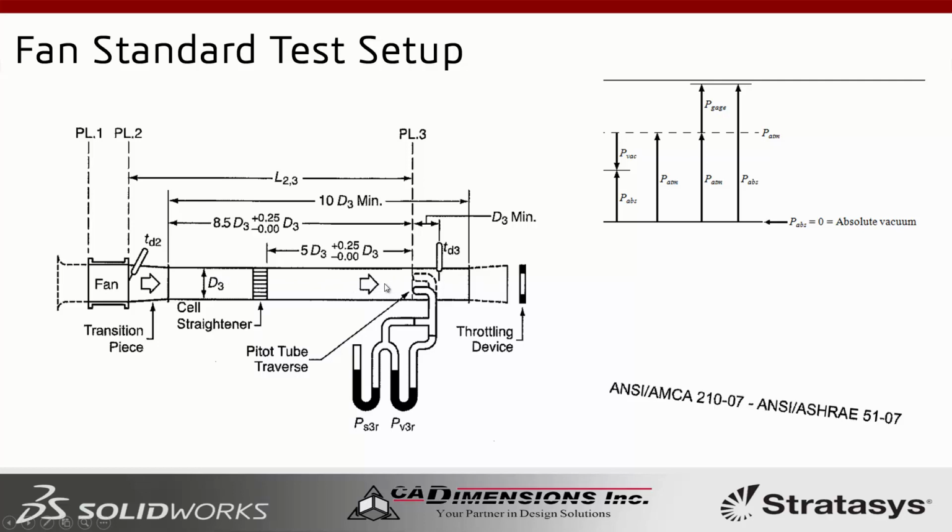As it flows to your outlet, typically you would have a pitot tube right here, and the purpose of this pitot tube is to ensure that you're meeting the right gauge pressure requirement. So this air will not just blow out into atmosphere. You would have a throttling device located at the outlet. In the real world, what I've seen is they might use a sphere, something that looks like a bowling ball at least, that moves in and out of the inlet.